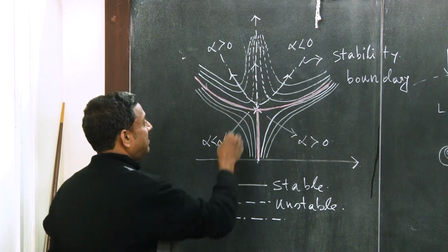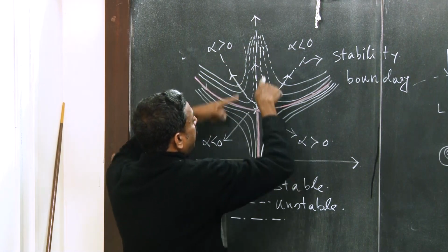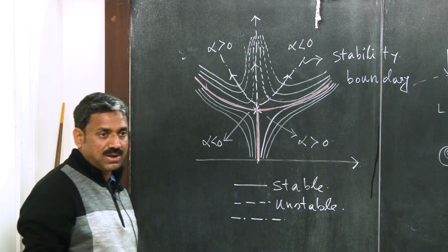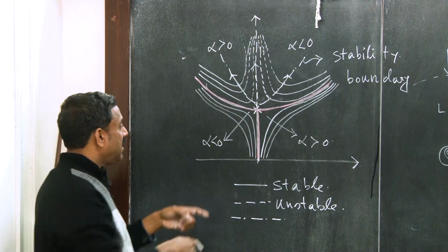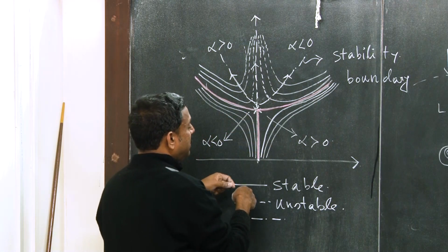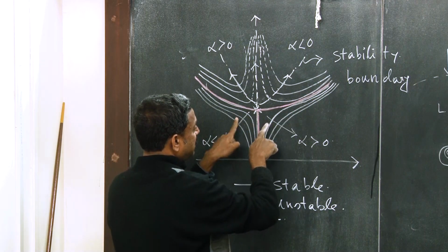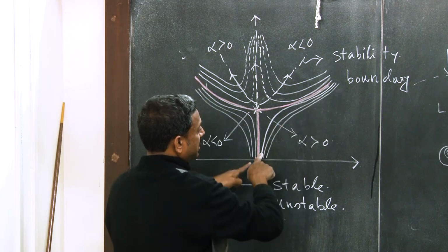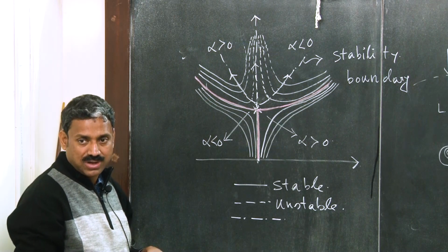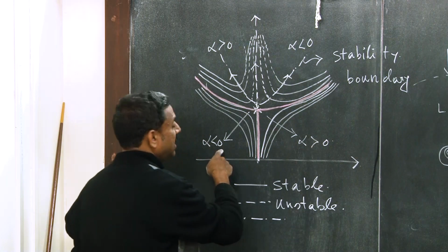Do you see that? And the fundamental path itself was unstable. See that this was unstable. These are all, even the imperfect systems are also unstable, and they are approaching this unstable fundamental path, theta equal to 0. You see that? Whereas beyond reaching the critical load, this was a stable path, and after bifurcation it is a stable path. The imperfect system equilibrium path is approaching them asymptotically. You know what an asymptote is, how to find an asymptote, right? And these are for different imperfections, alpha greater than 0, alpha less than 0.